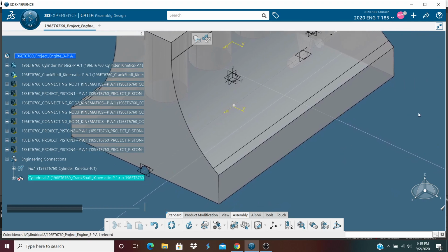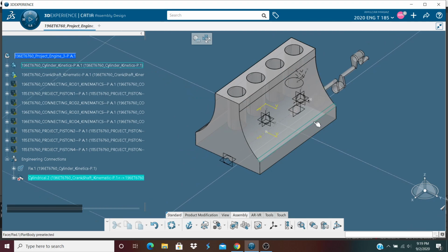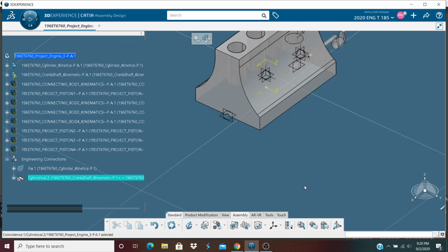the block is located. So we made them concentric, and normally you want 2 bondings on every connection, so the attachments will be solid and you won't have any movement whatsoever. The way to verify that the attachments are done is by checking the position in engineering connection.